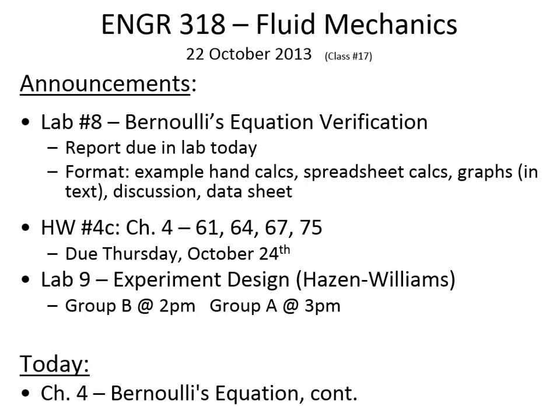So if the HGL was based on a couple of points, then what you should expect to see is the EGL will be very slightly above those points at first because the velocity head was small, but then it's a lot higher.